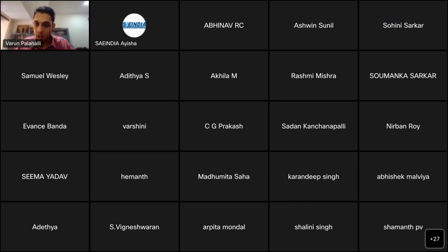Okay, all right. Then I have Wesley asking me, is it necessary to feature fasteners during simulation, or does surface contact make it enough? What is the difference it makes? Great question. Most often it depends on the kind of mounting condition that you have. These fasteners are already preloaded and bonded, and especially when you have a row of fasteners mounting one plate to another, you do not need to model fasteners.